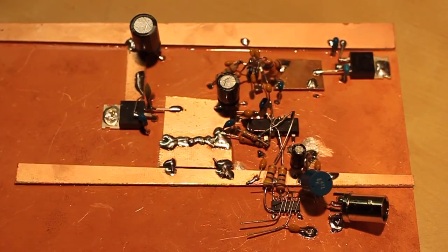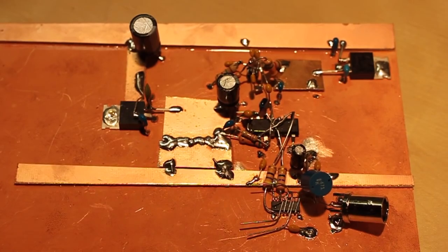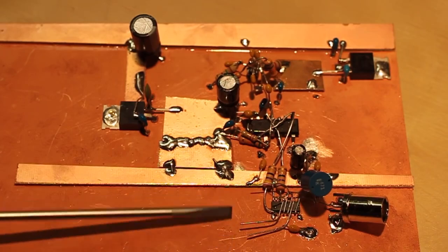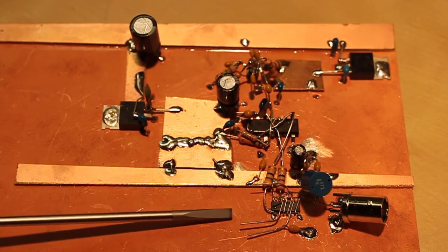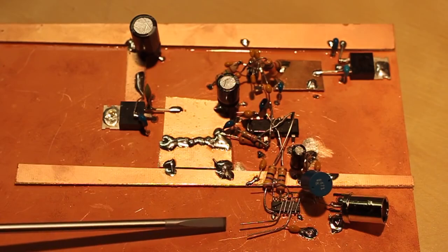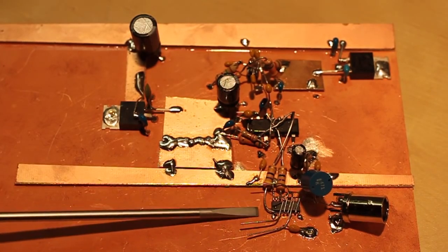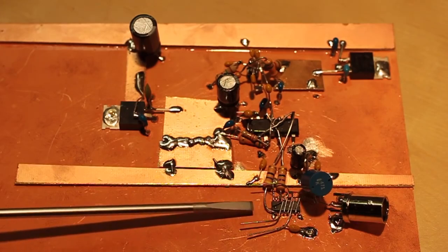So this 40-meter receiver project is shaping up quite nicely. Obviously, there's still some more work to do. I'll have to put in some work on the RF front end here and, of course, add some additional amplification and probably some filtering on the output of the mixer here. But hopefully this video has cleared up some concepts about quadrature signals and quadrature mixing, and specifically using the Tayloe mixer in a direct conversion receiver design.